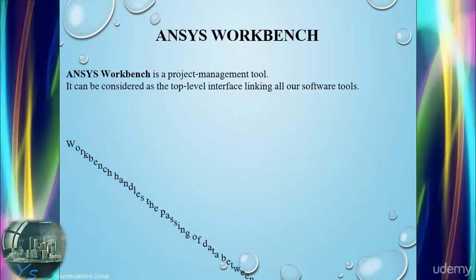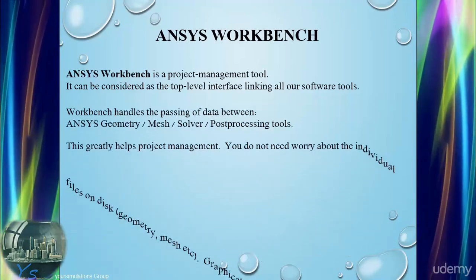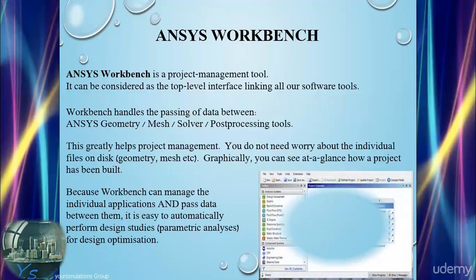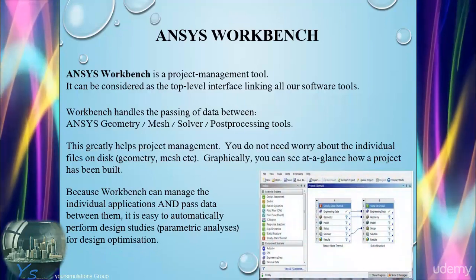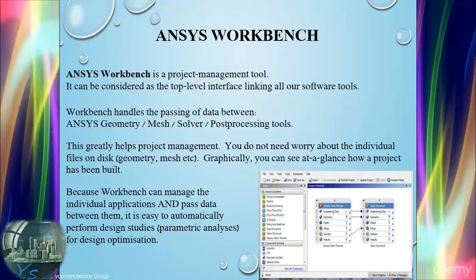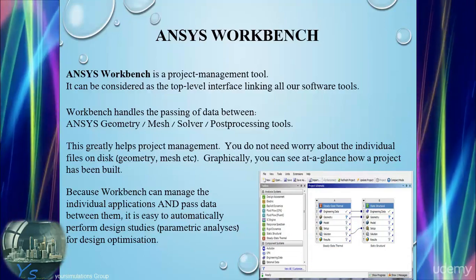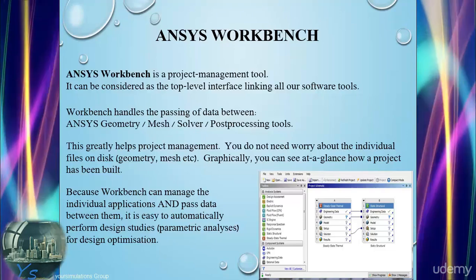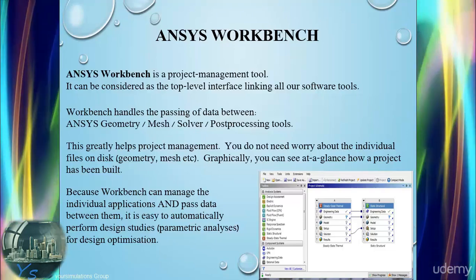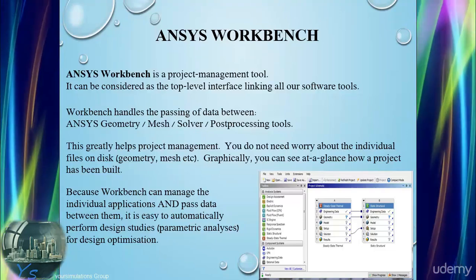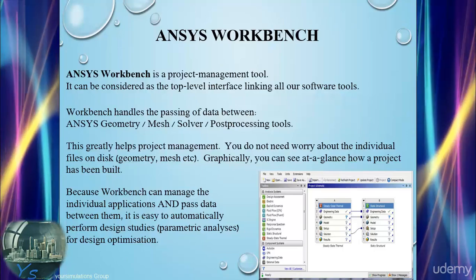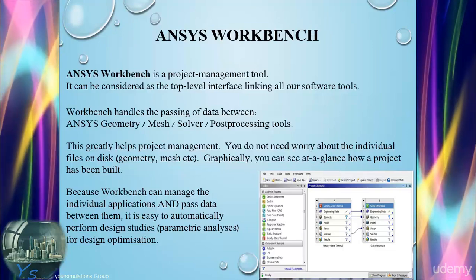So what is Workbench? Workbench is a project management tool that is used as a framework to allow all of the ANSYS products to communicate together. It handles the passing of data across the products, for example geometry, mesh, solver and post-processing tools, so that the user doesn't individually have to manage those files that are generated and required as part of the simulation itself.